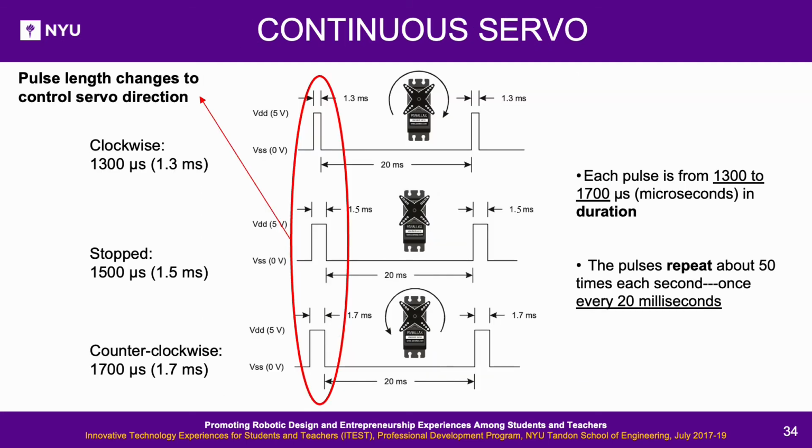Continuous servo. This is for a continuous rotation servo, not to be confused with the standard servo used in the previous activity. Wiring is the same for both standard and continuous servos, since the connector is the same. In fact, unless labeled, one may not be able to see the difference between a standard and a continuous servo from the same manufacturer. Alternatively, to figure out the type of servo, it can be interfaced with a microcontroller and a program can be executed to check whether the servo stops after rotating to the angle in the program or not.